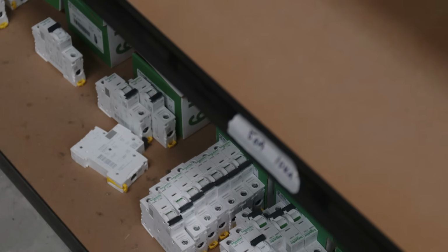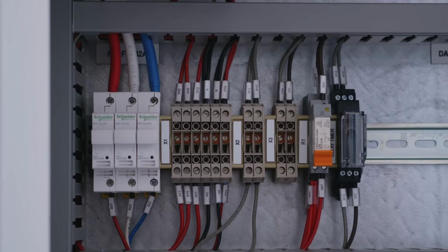Yes, it does. The settings of the circuit breaker would be in LSIG. L is long time. When it operates at nominal, and if the nominal current is exceeded, it might sustain until a particular period of time, that's called long time. Then S means short time.